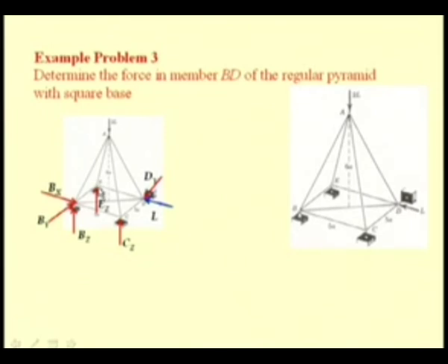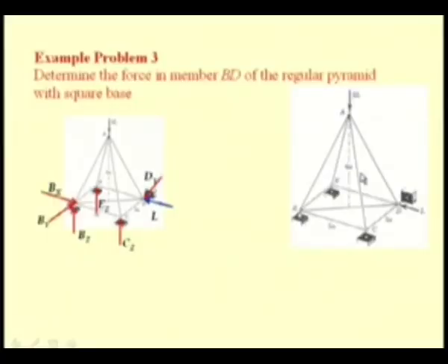Same is the case at joint E, where we again have a slender member. At D we have a horizontal member along the y direction and thereby we have a single component of reaction Dy. So, we see that we have a total of 3 plus 3, 6 unknown reactions to be determined, and from the free body diagram of the complete truss we have 6 equations, that is 3 force summation equations and 3 moment summation equations. Thereby it is possible to determine all the reactions.